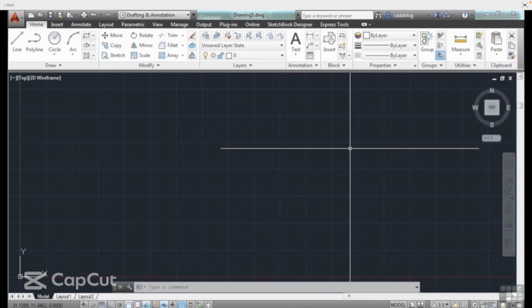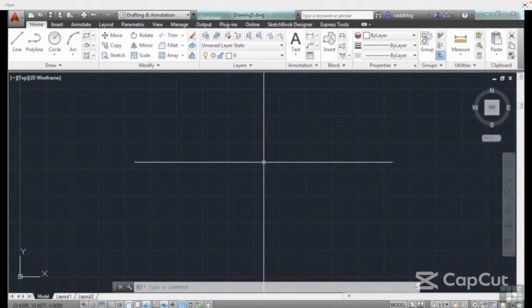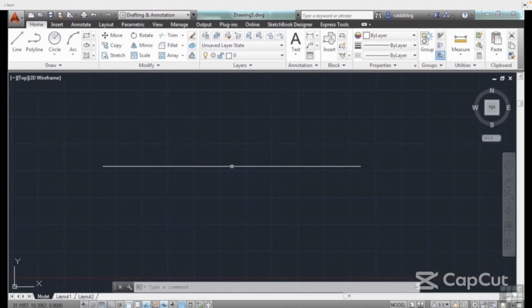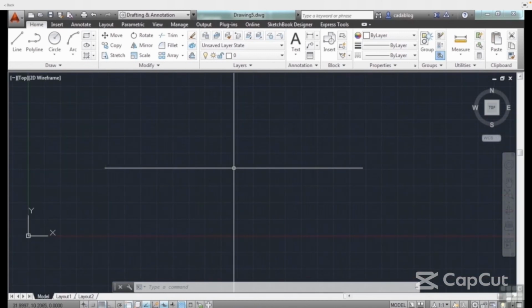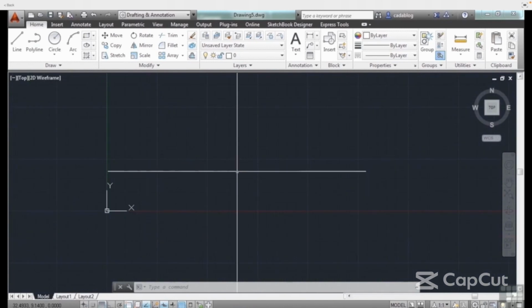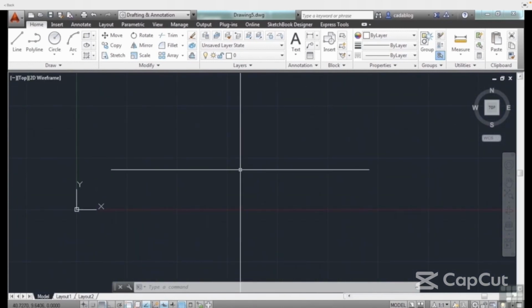With either of these commands, if you have made changes to the file but haven't saved the file yet, AutoCAD will ask you if you want to save them. Now, a change in AutoCAD, even for this case, could be as simple a thing as panning your drawing or zooming in or out. So if you open the file and zoomed out or just panned, that's a change from AutoCAD's perspective because you're changing the view. So that may come into account. You can click no if you don't want to save any of the changes, or just click yes.